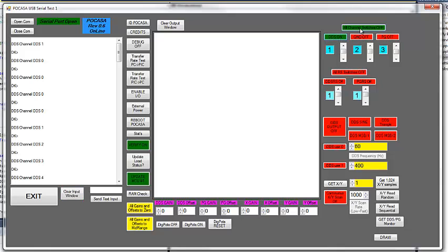You can turn them on, turn them off. You turn them all on. You hit this button to turn them all off real quick. Down here, the RS switches, that's the source resistance. Yeah, the lower the resistance, the more current you can push through the circuit at a given voltage. Same thing here, turn them on, turn them all off. They go to really high impedance.